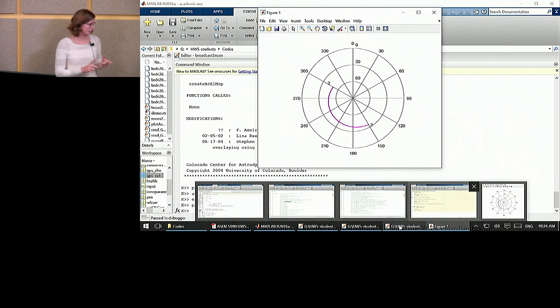Also, I want to mention something. I know most of you have had 50-50, and that class does a similar latitude-longitude to ECEF conversion. You can't use that one. You have to use the WGS84, otherwise these parameters won't be correct. Those parameters are specified in lecture 13. For geodetic, the flattening of the Earth and all of those parameters, you have to take into account. I don't think the 50-50 class does that, so if you're using 50-50 code, it won't produce the correct answer. Okay?